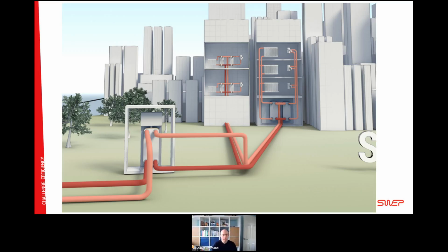So onto the application. A lot of you will be familiar with the sort of image on the left, and apologies if it's not too big or too clear for everyone. This is what we're used to seeing in, I would say, the majority of the UK market installations. We have the district energy or the network energy, if it's in the plant room in the building, coming in, going into each dwelling, and then in each dwelling we've got two heat exchangers, one for space heating, one for hot water. This is the typical approach, and this is quite common.